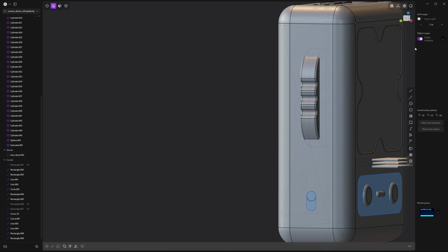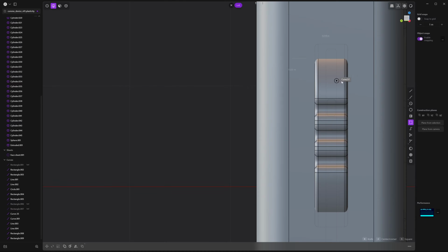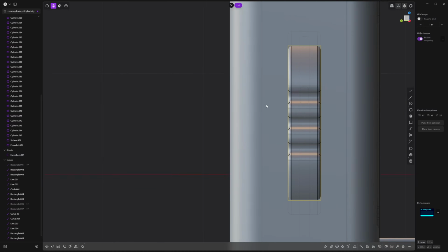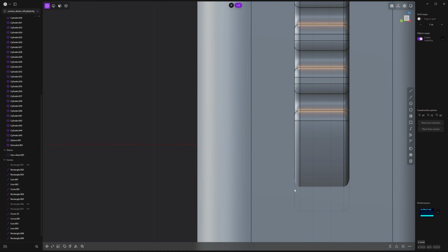And this does have to go in, so I might as well just create a rectangle here and use that as an opening. And I'm just clicking on the corners and then it's snapping to the edges of the actual shape. Next, press 1 and select all these points so you can apply a bit of a fillet so it matches that curvature of this. Hold Shift if it's going too crazy.